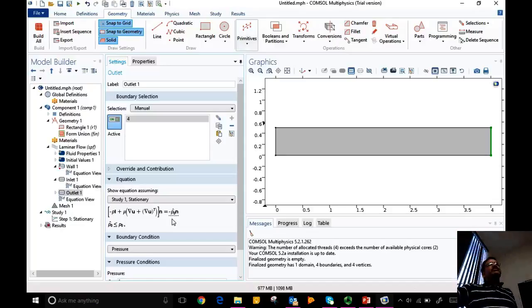It may start dripping through the bottom side, right? So what happens at the exit outlet, its impact can propagate a little bit into the domain, but it propagates less and less at higher and higher velocity. So there is a kind of boundary layer at the exit, the thickness of which depends on the advection velocity. If you are advecting a lot, then you don't have to worry about the outlet boundary condition. And we will see the impact of this in our solution as well.